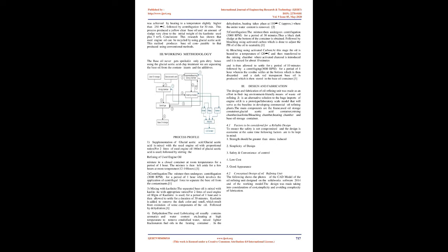Bleaching. The acidic oil in the beaker was then subjected to bleaching. The oil was placed on a regulated hot plate and the temperature was maintained at 110°C. 6 wt% of industrially produced bleaching earth was introduced into the oil and the mixture was continuously stirred for 10 minutes. At the end of the bleaching step, the bleached oil was neutralized.